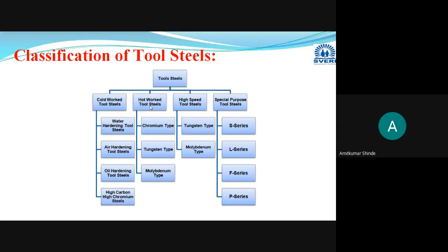The temperature at which old grains break and new grains form is termed the recrystallization temperature. It means there will be some change in its crystal arrangement, that is, the orientation of grains will change. That particular temperature will be termed as recrystallization temperature.